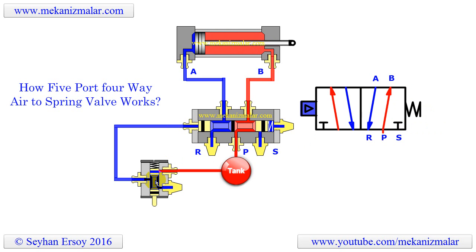Please note that we have 1 valve at the left side of the main valve. I call this valve a 3-port, 2-way, force-to-spring valve. While the 3 ports and 2 ways description will be obvious based on our previous description, the force-to-spring term needs an explanation. It means that we can actuate the valve by force.